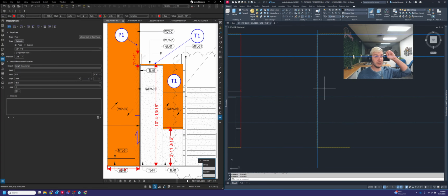Referring back to our initial panel hardware video, we did some discussion on panel hardware and what is required for the gap between the back of the panel and the face of the wall behind your panel. If you are using the standard panel cleats like we're using here, you need to provide a 1-inch gap between the wall and the back side of that panel. If you are using Z-clips, Z-bars, Monarch Metals Incorporated hardware, you want to show a 1/2-inch gap minimum between the back of panel and the face of the drywall.